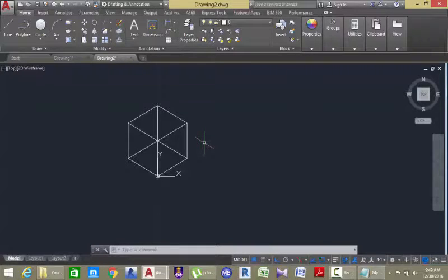But when you look at objects in the real world, some of the edges that are away from you cannot be seen. So to get a realistic look of this cube, select this line and erase it. Then select these two rectangles and go to the Home tab, Modify panel, select the Explode command. Now select this line and erase it. Turn off your grid.